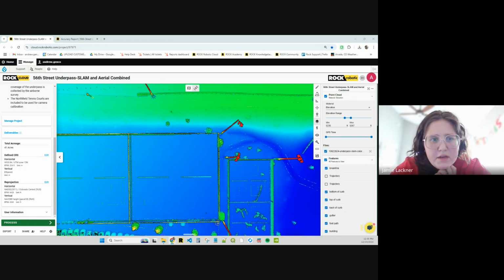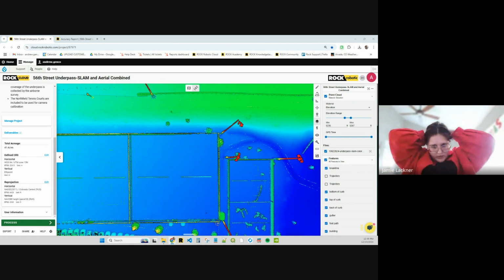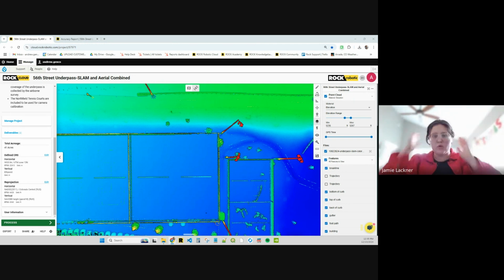I honestly will say, I thought your question was going to be more like, how do we get those into Civil 3D? But the biggest thing is you can export whatever file type you need. I know LandXML is one that gets in pretty seamlessly with Civil 3D. That is an exportable type. I also have known people to just take our contours and build the surface in Civil 3D from our contours. We also can generate a PLY file type, which is closer to a TIN. It's just more open source, and that can help generate it as well.